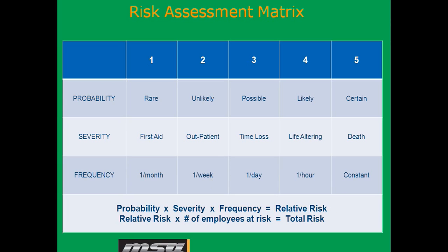But what if I was doing a different task? Let's say I'm changing knife sections on a cutter bar. Well, the probability of me being injured is a 4, because knife sections are very sharp, and I'm working amongst the guards, kind of in a confined area, and guards are pointy and sharp as well. What about the severity? In that situation, it'd be a 1, first aid, because a couple Band-Aids would be all the medical treatment that we would need in a situation like this.